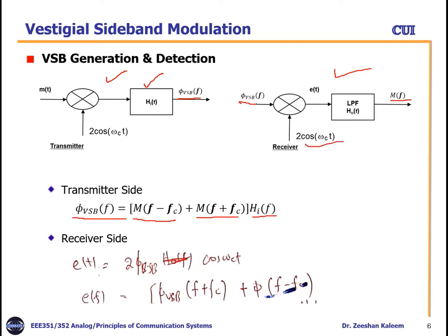But we have a 2 here to balance the term at the receiver side. This is just for balancing. We already discussed in detail in double sideband modulation. So this φVSB, we are passing the 2 cos ωct to the product modulator. So we just again multiply this one.